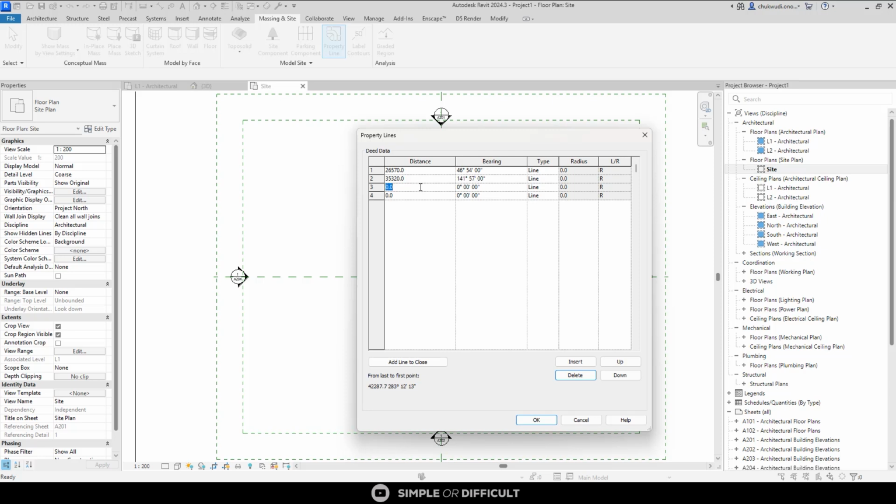26570. Then for the bearing, right. So I mistakenly deleted my degree. Wow. So we're going to have to add it, right? Now the next bearing, let's just continue. 226. To add degree, just hold Alt on your keyboard and, while holding down the Alt, press 0176. That is going to add it for you.